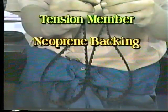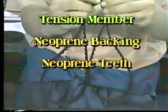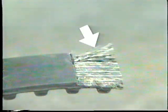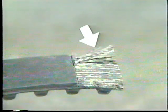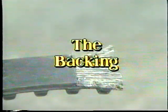Timing belts come in a wide range of sizes, but all of them have 4 basic parts: the tension member, the neoprene backing, neoprene teeth, and nylon facing. The tension member, the muscle of the belt, is usually made of carbon steel or fiberglass. It provides the strength needed to prevent the belt from being ripped apart while the drive is operating. The neoprene backing of the belt is the layer just above the tension member.